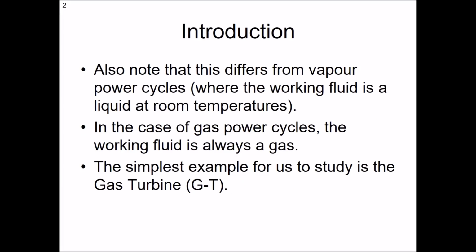So this also differs from vapor power cycles, because the substance going through our turbine is always a gas, and that's why they're called gas turbines. Now, there's a lot of misnomer floating around in this particular area of thermodynamics, because quite often people think it's gas turbine because gas is the fuel. But that's not correct. It's a gas turbine because the working fluid is always a gas. Okay, so if you're having difficulty, remember that. Just think a wind turbine works with wind, and a gas turbine works with gas. It's always gas. Now that differs from a vapor power cycle, where it's a vapor going through the turbine.